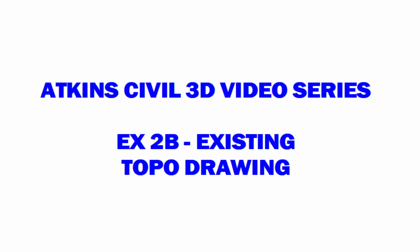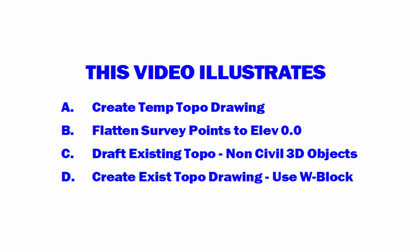Atkins Civil 3D video series, existing topo drawing. This video illustrates: A, create temp topo drawing; B, flatten survey points to elevation 0; C, draft existing topo non-Civil 3D objects; and D, create existing topo drawing using W block.